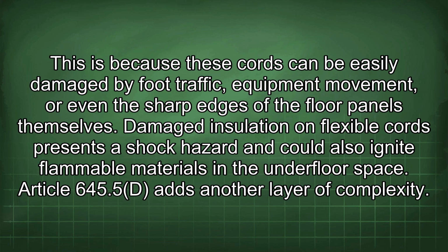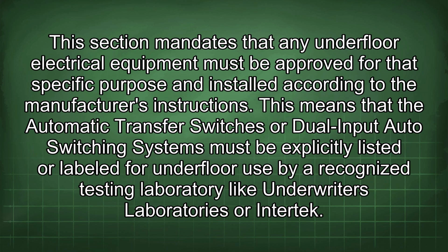Article 645.5(d) adds another layer of complexity. This section mandates that any underfloor electrical equipment must be approved for that specific purpose and installed according to the manufacturer's instructions. This means that the automatic transfer switches or dual input auto switching systems must be explicitly listed or labeled for underfloor use by a recognized testing laboratory like Underwriters Laboratories or Intertek.